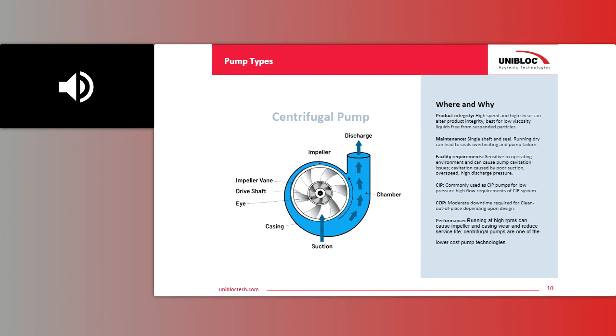So centrifugal pumps are one of the lower cost pump technologies on the market. It's typically limited, again, to mostly thin liquids. Most centrifugal pumps are good up to about 500 centipoise. Anything over that, this technology is not typically applicable. They are designed for basically high flow applications, low pressures. They are not designed for thicker products. Definitely, you don't want to pump solids with these. It will definitely damage any solid particulate you may have. And then their pressures are relatively low on this technology.